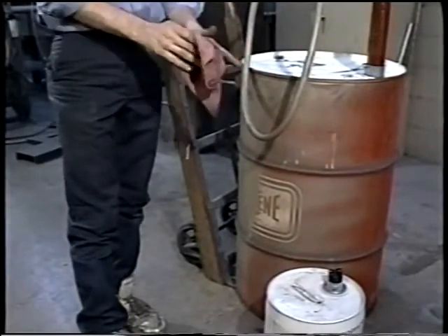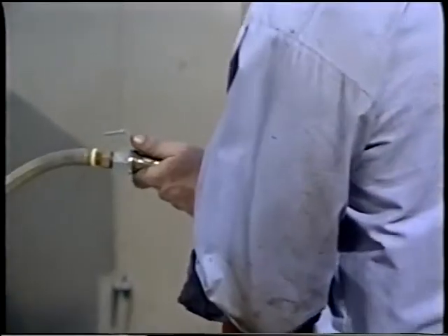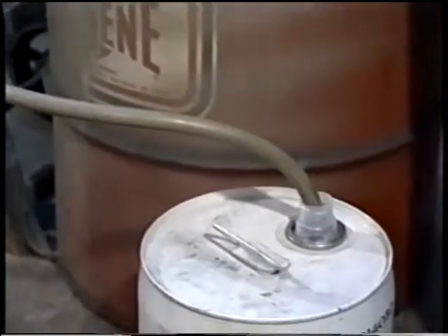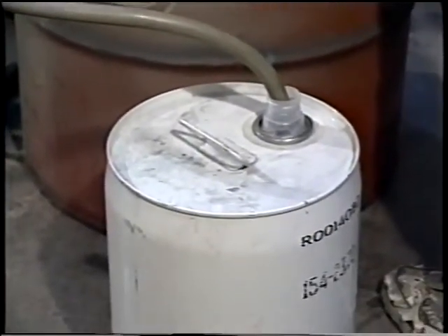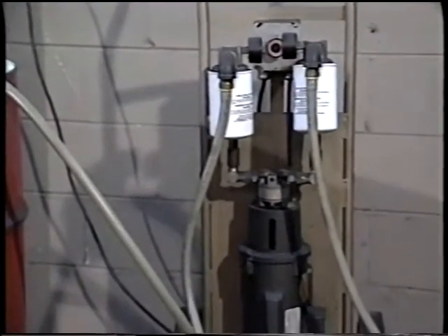Even the fluid itself can be a problem. For example, new hydraulic fluid straight out of the drum has usually only been filtered down to about 50 to 70 microns. It may not have been filtered at all. If you have a system which requires, say, 25 micron filtration, then the fluid from the drum must be filtered before it goes into the system.